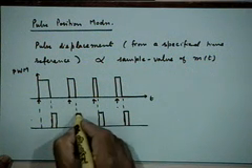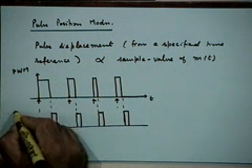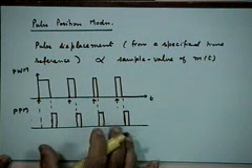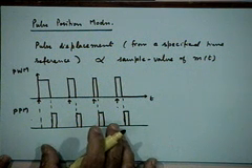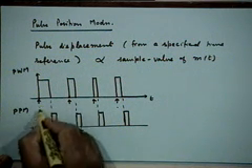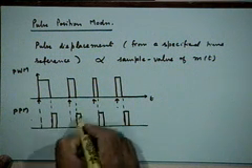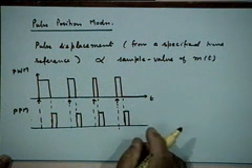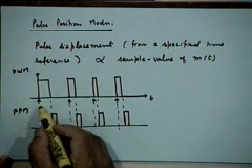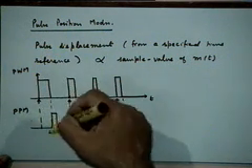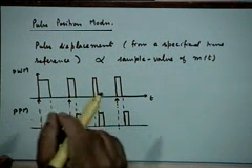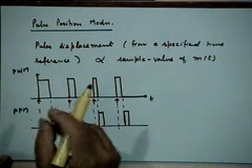This is the kind of waveform you are looking for, right? This is your PPM waveform. So any idea how we can generate that? Is it clear? This is what we want. Yes, but you have information about where my pulse is starting also. Yeah, this is true. This is the information about pulse starting. So, differentiating. All right. If you differentiate, you will get two pulses, a positive edge and a negative edge. What do you do with that? Remove the positive edge, and then you have a negative edge, and that has to be converted into a positive pulse of this kind somehow.